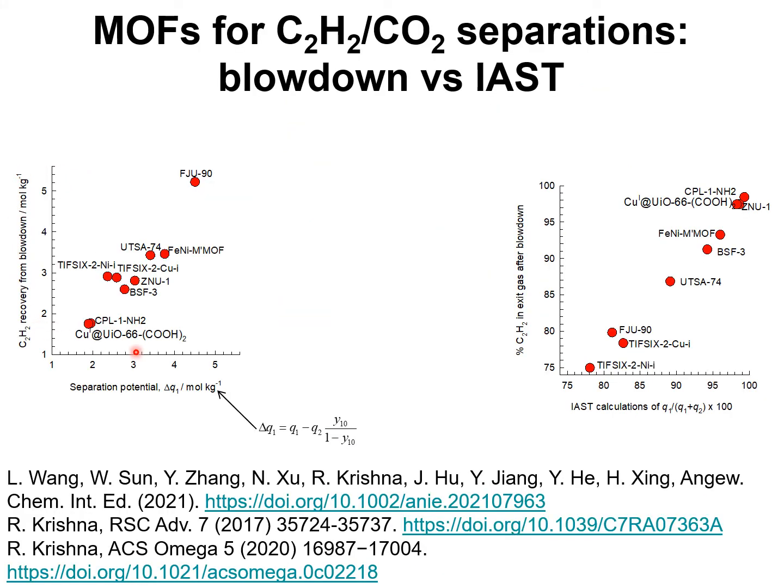In this graph, we plot the C2H2 recovery from blowdown operations against the separation potential determined from the IAST calculations. For all the MOFs, there is a roughly linear relationship between the product recovery from vacuum blowdown and the separation potential, indicating that these IAST calculations provide a reasonably good measure of product recoveries.